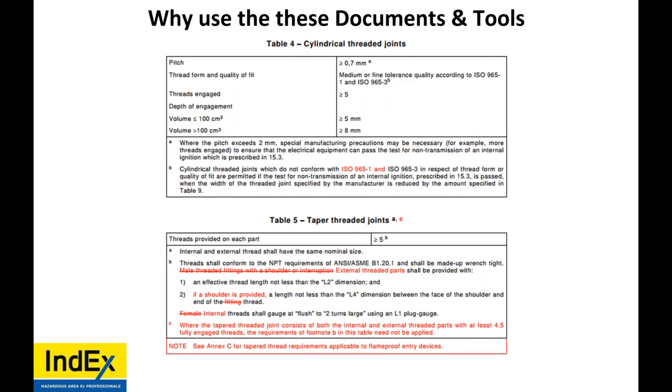Torque settings are generally on the cert or IOM. Correct, but 14 is for inspection. So if those torque settings have been done correctly, well, then the previous ITR, inspection test report, shall be cited by the inspector. Now, if we're talking about operations and maintenance, that person has to know how to open and close that box correctly, or the protection technique is null and void.